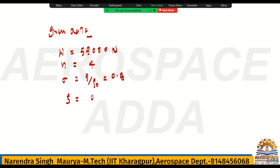So you can calculate what is the rho. It is 0.8 into rho naught. What is the rho naught? It is 1.2. Rho naught is the sea level density. So sea level density, it is pre-assumed. If it is given, okay. If it is not given, it's also okay. Why? Because it is the sea level value, and that value you must know. So now you got here 0.96 kg per meter cube. This is the density at some altitude, because density ratio they have given, it means the aircraft is flying at some altitude.